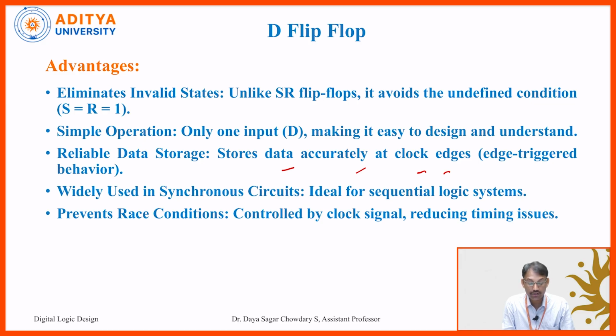And it is widely used in synchronous circuits. We already discussed that synchronous circuits means all the D flip-flops are connected to a single clock signal. And it prevents race conditions. So there is no race condition here, because it is controlled by the clock signal, which means timing issues are also reduced here.